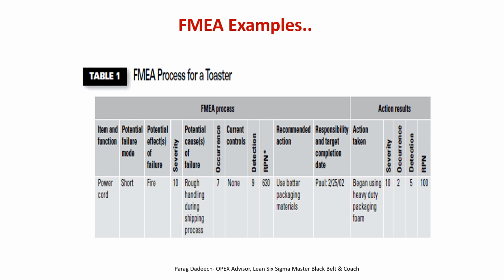Thereafter, you take some actions to mitigate the risk, such as deploying better packaging. In this particular example, the severity, however, remains the same because in case of failure, the effect will be fire. It is not going to change. So the severity remains 10. However, the occurrence of failure reduces significantly due to better packaging, so the occurrence rating is reduced to 2.